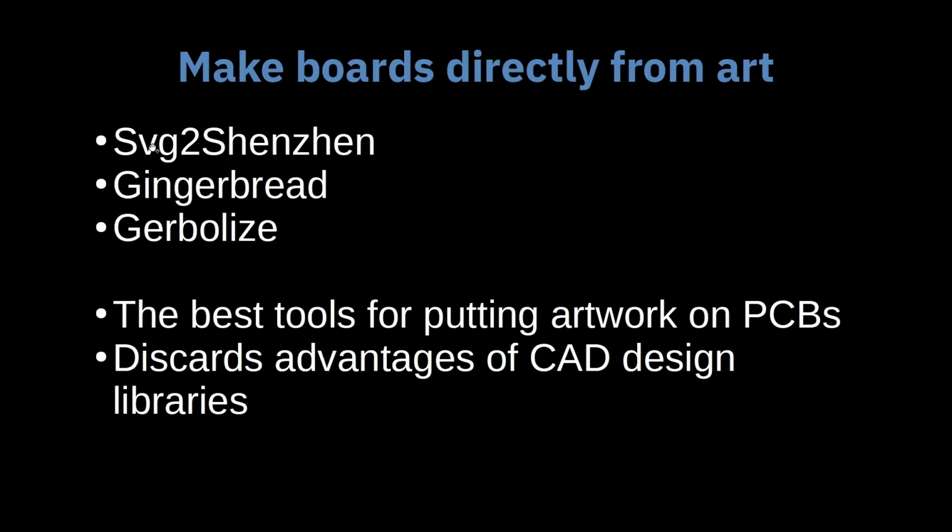control things like our footprints. Like we wanted to know that when we made this LED this specific way, when you put the LED on the board, the footprint for it has to be just right. And for us, this is important because we are producing these in mass. If you're making a couple, you can just make everything big and then do it by hand, and it's no problem. So the major reason why we were frustrated by these tools is just that we wanted to integrate our artwork with a DRC check, right?